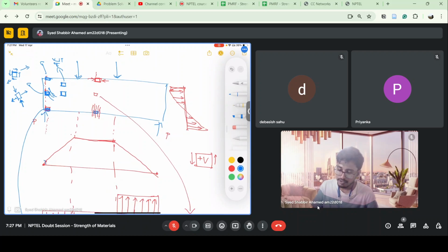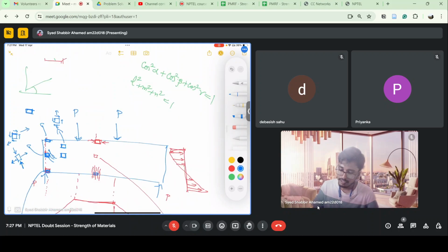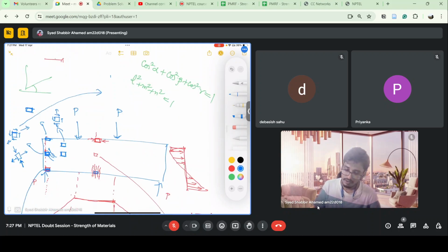Like if I draw the Mohr circle for this, we know that we'll have zero normal stress, shear stress, zero normal stress, shear stress. If I draw it like this, it is at 90 degrees in the Mohr circle, but in the actual structure it is 45 degrees with respect to the initial plane. I'll get a tensile maximum principal stress and a compressive minimum principal stress.